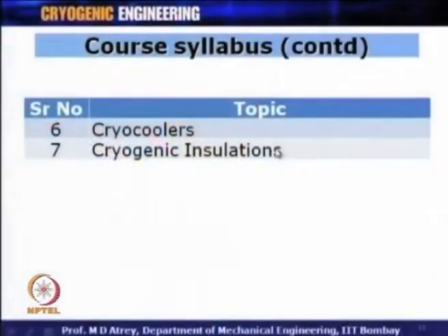So, to minimize that, what is most important is the insulation. Insulation is a critical part of cryogenics, and depending on the low temperature I am talking about, for example, 80 Kelvin or a very low temperature of 4.2 Kelvin, I have different types of insulation, in different forms like perlite powder. It could be vacuum insulation.